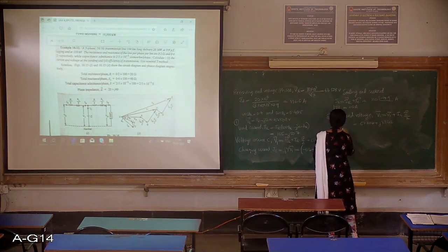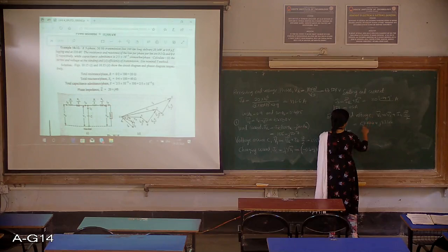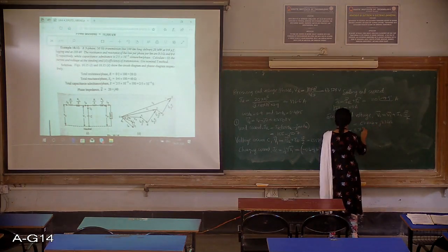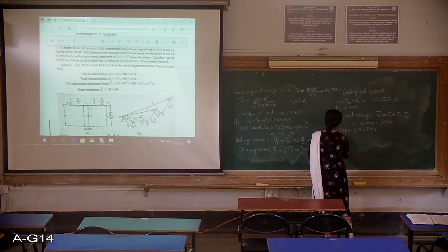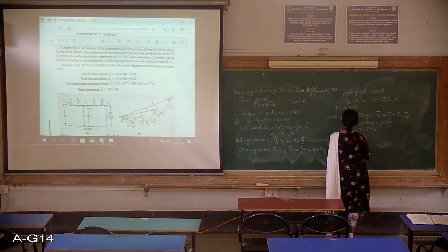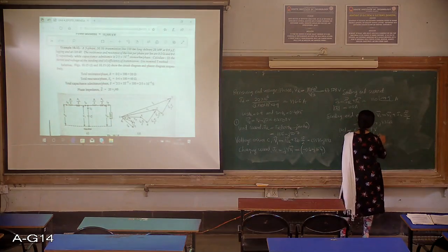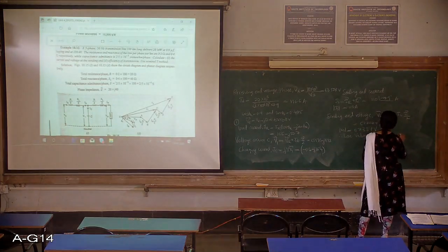Okay, so your magnitude of Vs will be, you square it, square root of this square plus this square. So it comes out to be 67,387 volts. And then what will be the line value? This is the phase value because you have considered per phase there. So line value, multiply by root 3, that's it, line value of sending end. So this is one care that you have to take here of sending end voltage.